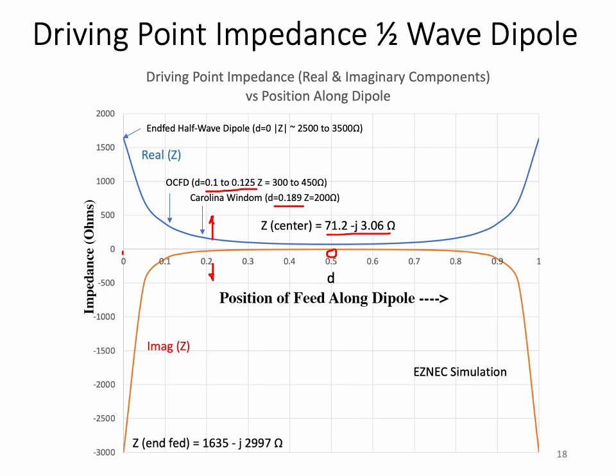For our application, namely a vertically polarized half-wave radiator for handheld use, an end-fed configuration is ideal as we obviate the need for these really bizarre and special mechanical structures to attach the feed line to the radiator. However, we don't want to use a bulky transformer as used in end-fed half-wave horizontal antennas. So how do we transform this high impedance to something in the order of 50 ohms?